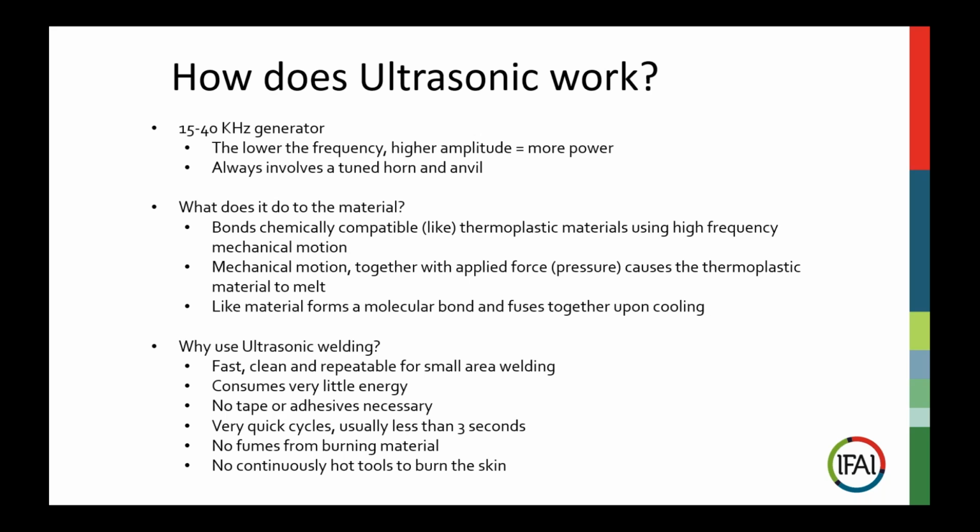It's fast, it's clean, it's repeatable, but really it's better for small areas. It gets very expensive when you try to extend it to large areas. There's usually no tape or adhesive necessary, especially with the polyethylenes and polypropylenes. And there are no fumes from burning the material when welding it. And the tools do not get hot to the touch.